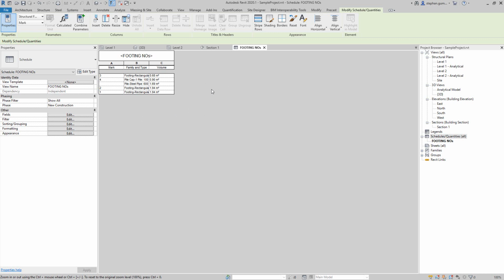And this is important because these schedules and these views are live to the drawing, and it's these views that are moved and dragged or placed upon a drawing. So the views and schedules that you create are live to the actual model, even on the drawings. And this is a key difference between working in that BIM space versus in that 2D AutoCAD or even that 3D AutoCAD space, where you're just using solids to do one thing versus the next.